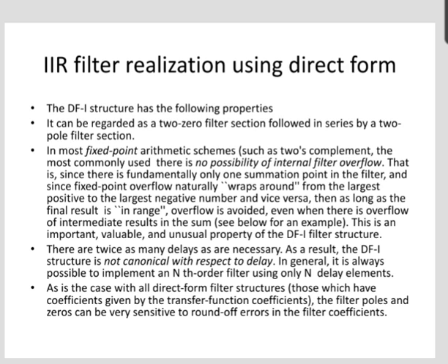This is the same numerical sensitivity that polynomial roots have with respect to polynomial coefficient round off. The sensitivity tends to be larger when the roots are clustered closely together. To minimize this sensitivity, it is common to factor a filter transfer function into series and parallel second order sections.